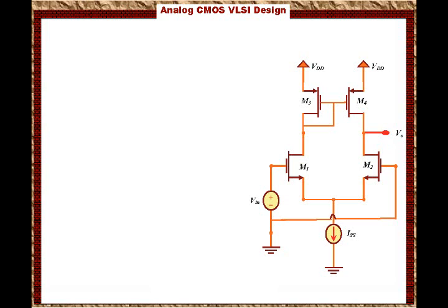Now let us discuss the large signal analysis. Basically, we are asking: if we swing the input voltages by large values, what happens to the circuit? So we are interested in the first case now. If Vn is bigger than twice the threshold voltage, that means we have enough voltage to turn one transistor on or off without the effect of the bias and current ISS. Under this condition, the input voltage is large enough such that M1 is on and M2 is off.